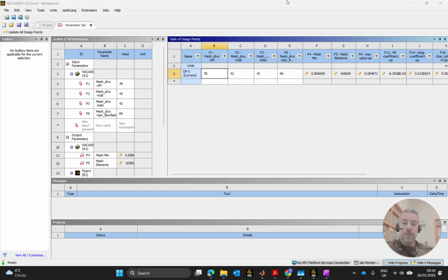So the grid independence is so much more whenever you use the grid convergence index method. It becomes so much more than just determining a grid refinement level at which the value of the variable of interest becomes independent of further refinements of the grid.